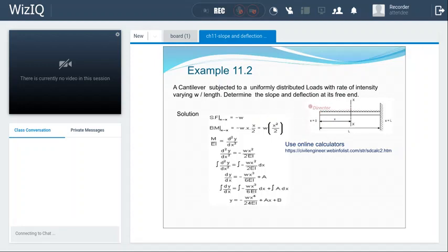Shear force, you can say it will be W here, and then we find this value. This value can be calculated here. Bending moment at section XX is minus W into x, the load here, and this distance is x by 2 from the centroid of this load.